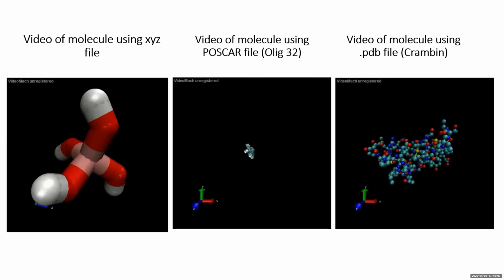And so once we run this particular simulation, that particular bond will change its distances based on the simulation. And if you want to plot it, once again we will go to that label thing, where we can plot the bond, or we will get the data for it based on the frames.